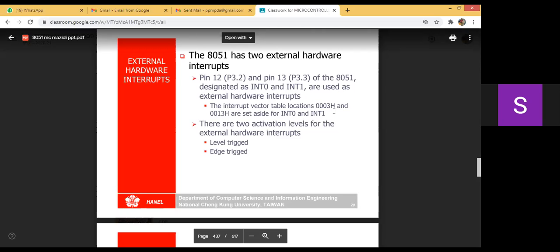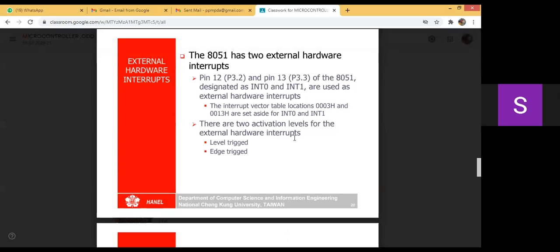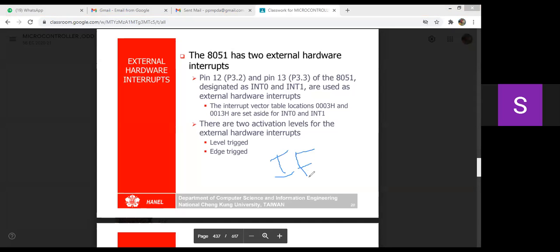Okay. So the timer related interrupts, timer 0 and timer 1, will be activated based upon TF, the timer flag. Friends, please remember, because the exam is offline, I already explained: TF, the timer flag. Based on the TF, the timer will be activated. Then we have to set 1 into IE, the interrupt enable register. Any interrupt will be activated this way.